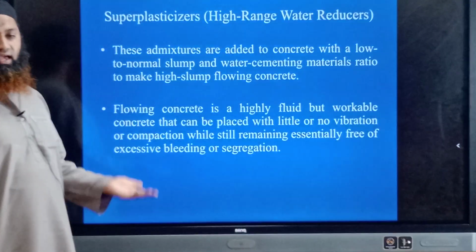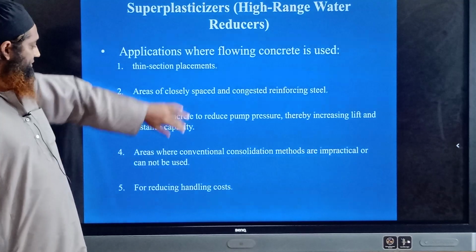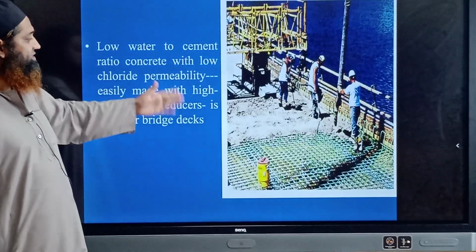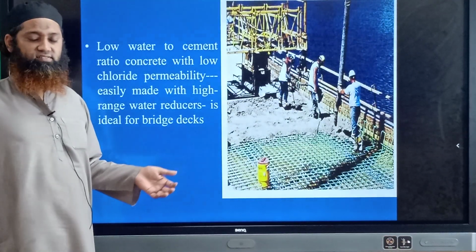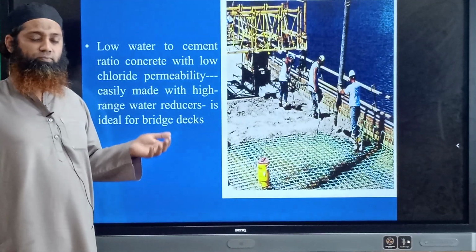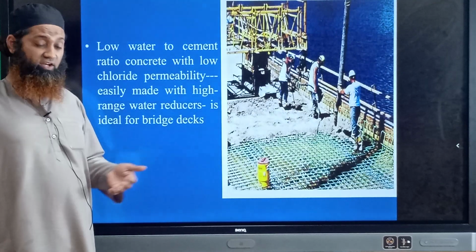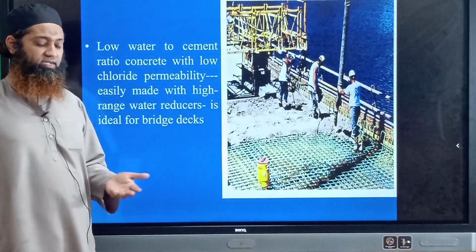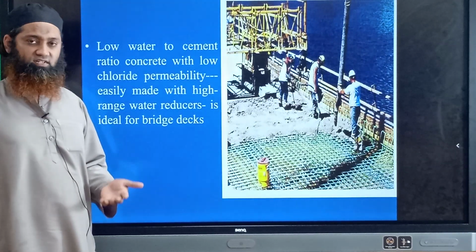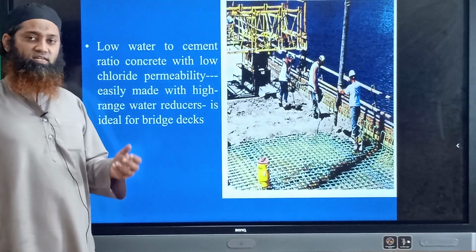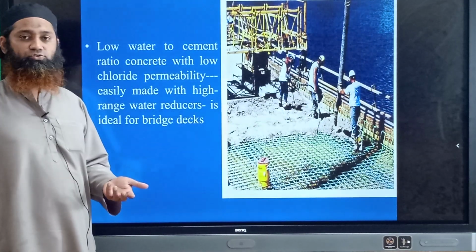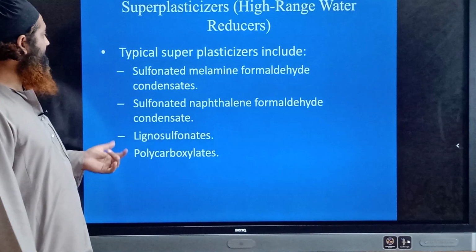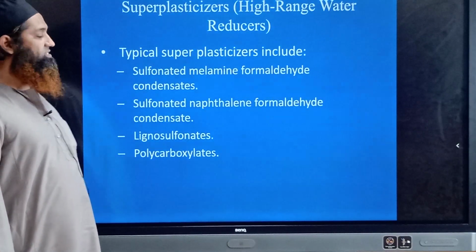Why do we add it? As I had explained very specifically in my previous session. Let us see here. We had seen how this type of plasticizer is added into the concrete and how it performs. Thereby the free flow of concrete is achieved, and the strength is also gained: the split tensile strength, as well as compression strength and flexural strength. The desired strength is obtained, as well as the free flow of concrete. Let us see further. What does this super plasticizer contain?